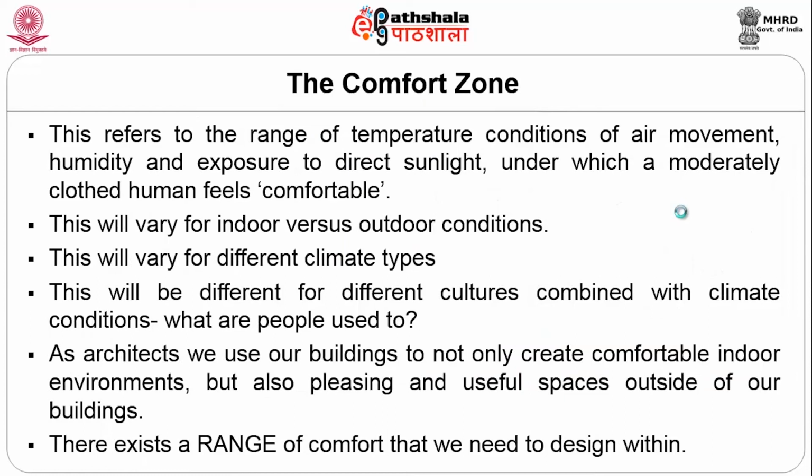The comfort zone. Now, this is something all of us use very frequently when we talk about a building and design a building. Irrespective of the building being in a cold climate or a warm climate or a hot and humid climate, the comfort zone for human beings relatively remains around the same region. Of course, people are certainly acclimatized in those areas to a different kind of comfort zone.